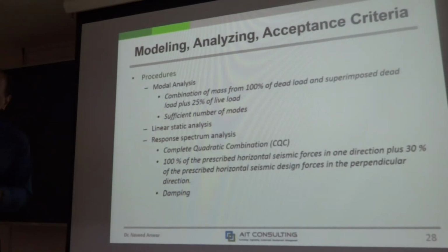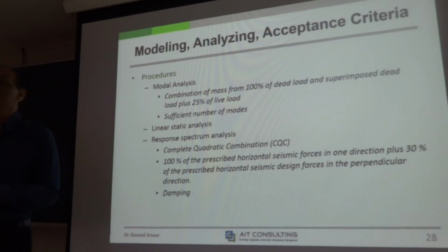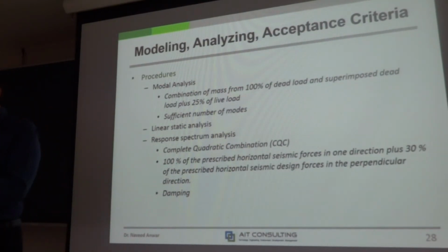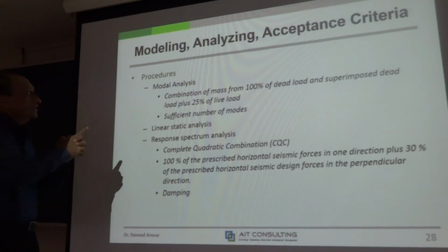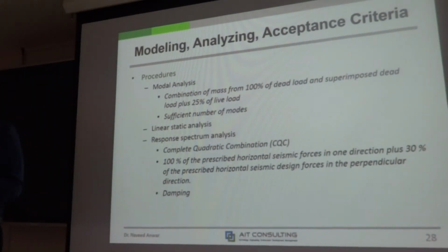Not dead load analysis, which is required, but modal analysis, because we define a tall building as a building which is governed by lateral loading, and lateral loading is related to modal analysis. Have you already heard about modal analysis? You know what it is, right? Fine. So modal analysis is the first one to be done to understand what's going on, which will then be used as a basis for all other work.